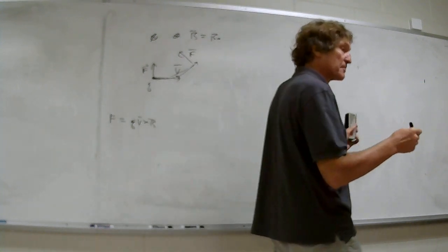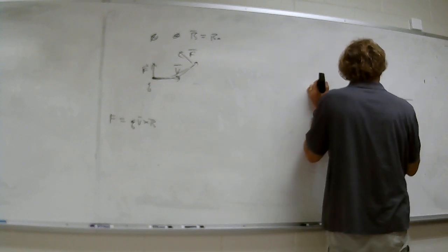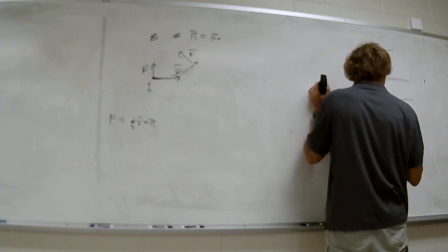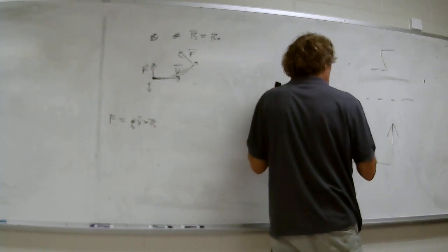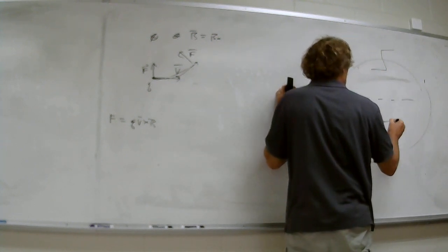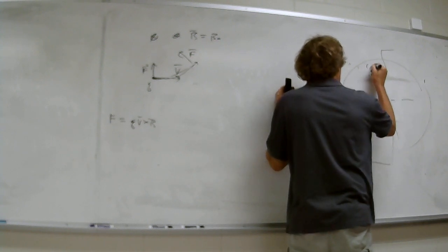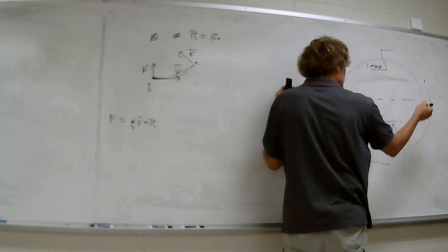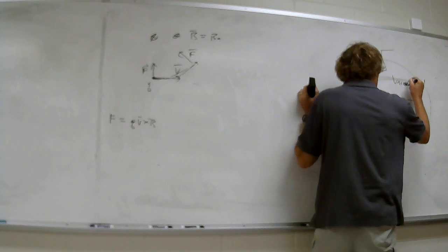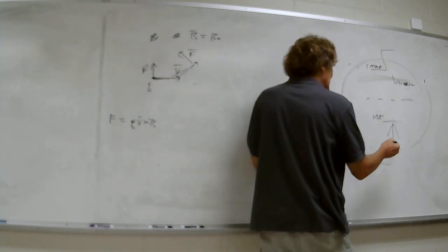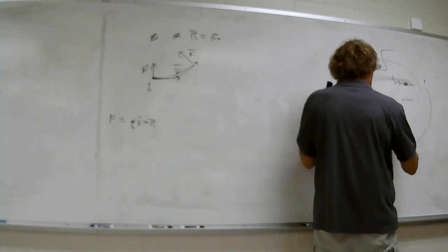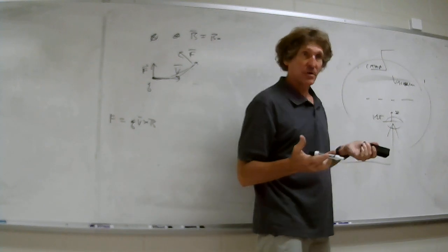A vacuum tube is something at a very low pressure, and you have sets of grids. Really, we just use a triode. What they do is have a cathode here and a hot filament here. This is inside, a hot filament right here, and this is a cathode. It catches this thing. This is a vacuum in here, or actually close to a vacuum. But what happens is this cathode gets really hot. It'll glow red. It's called thermionic emission. It'll emit electrons from there.